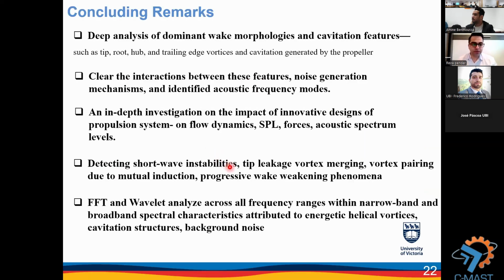As a concluding remark, in our work, in the first step, we deeply analyzed the dominant wake morphologies and cavitation features. For example, wake structures like tip, root, and hub, and cavitation like sheet cavitation, hub, and tip cavitation.